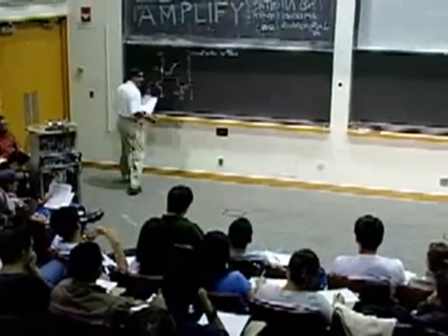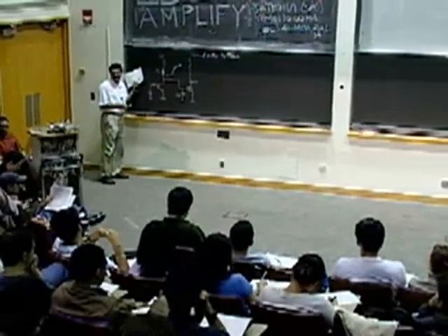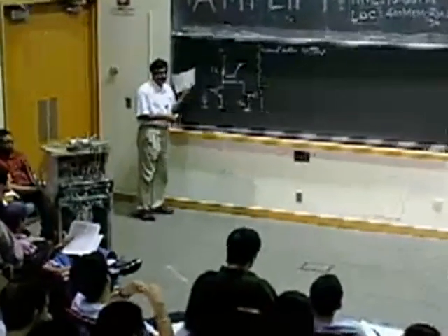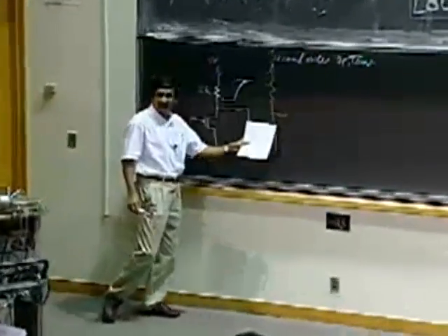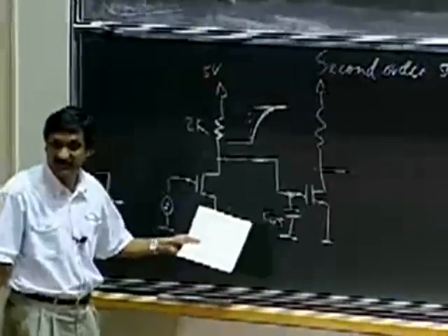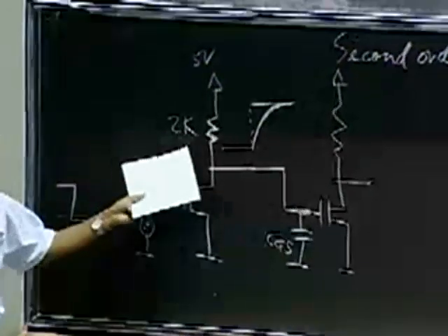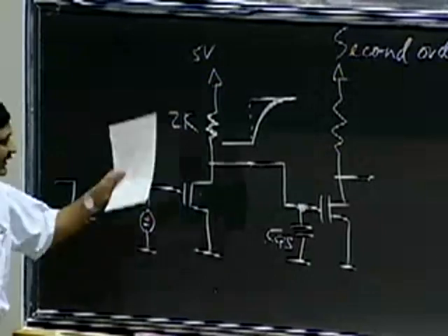Decrease the time constant. And how would you decrease the time constant? The capacitance is connected to this MOSFET gate here. I didn't want it in the first place, but it's there. I can't help it. So I can decrease the resistance. Okay? Good. Let me go ahead and do that.